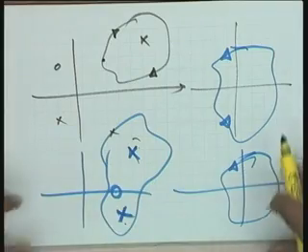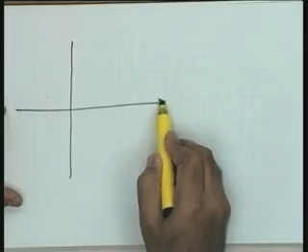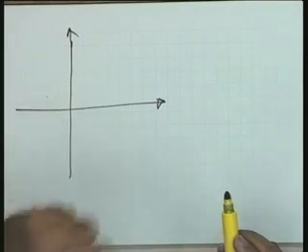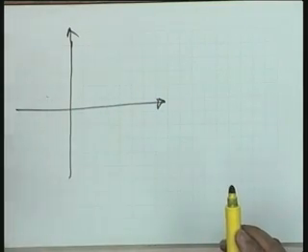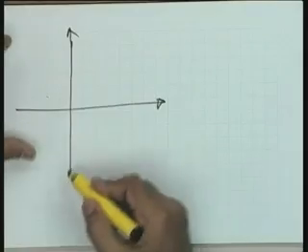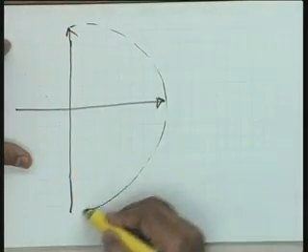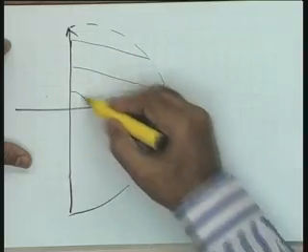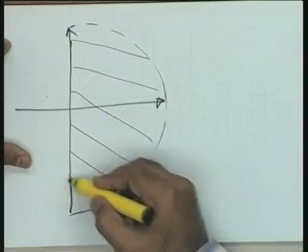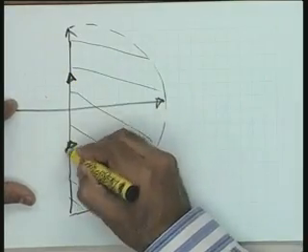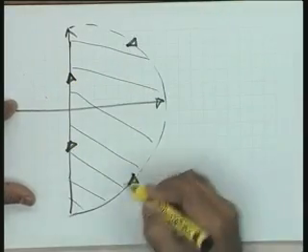Now I think the picture should be clear through this, and I hope you will be able to state the Nyquist stability criterion now. I will leave it open and try to get the criterion from you as to how to test the stability. What I want to say is this, that the S-plane contour which I have thought of is now the complete right half plane, though it is an infinite contour. How to handle this situation, I will come to this later. The complete region, and therefore, this is the contour which I want to travel in the clockwise direction.